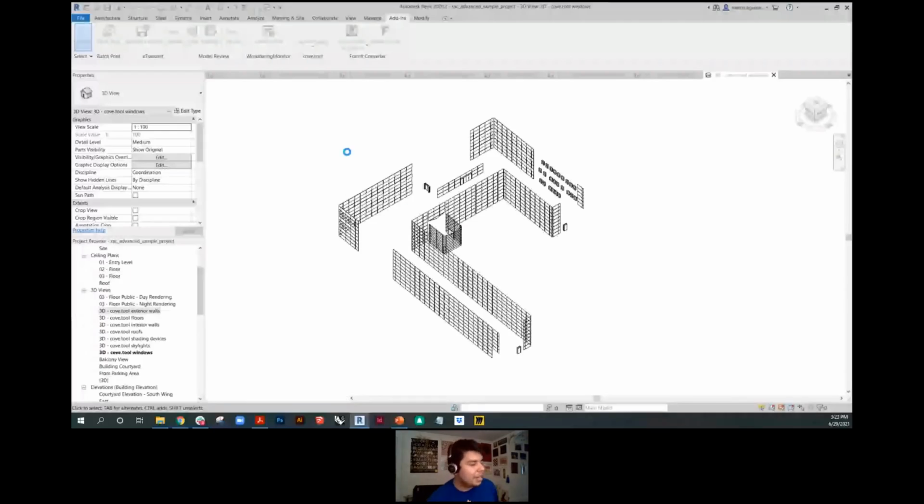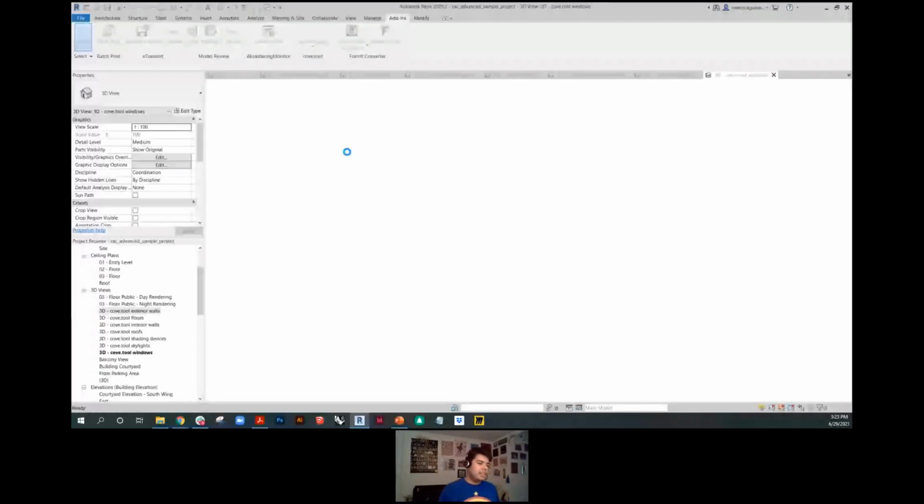And now we'll wait for the plugin to start sending all of that information over into the app. The only information that the plugin is collecting is surface area and object orientation. Things like assembly properties, U values, R values, all that kind of stuff that you could attribute to an object, none of it is being exported. We're just assuming that most users are poorly attributing their geometry, and this is a very quick, dirty model, not necessarily closed or anything like that. So once you're back in the tool, all of that is taken into account. We'll clean that geometry, and you can apply all of the different properties once you're inside of the energy page.